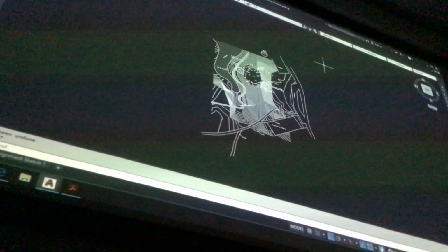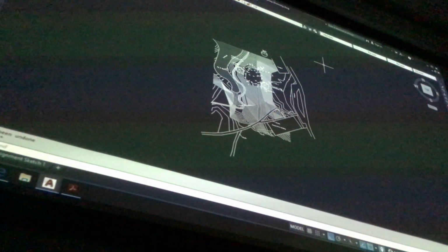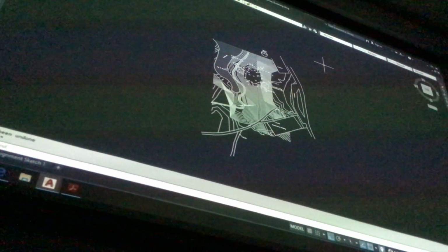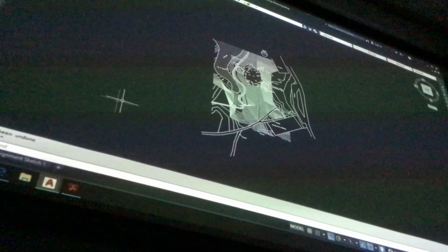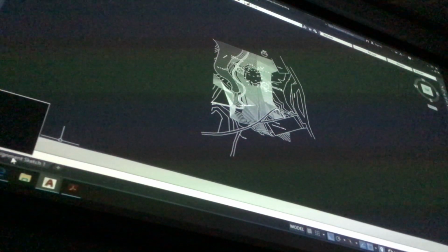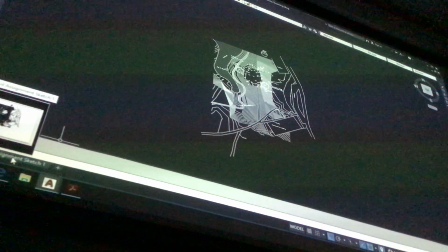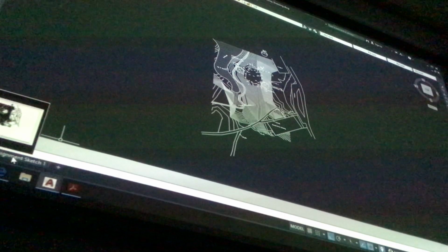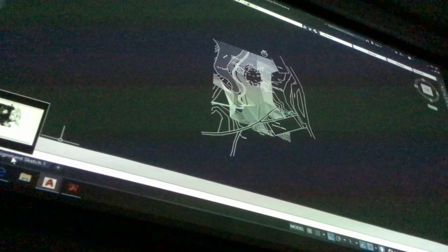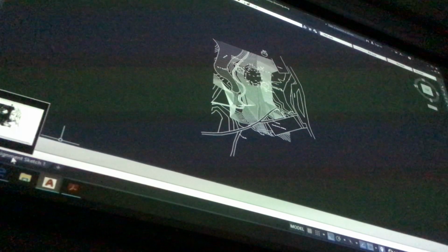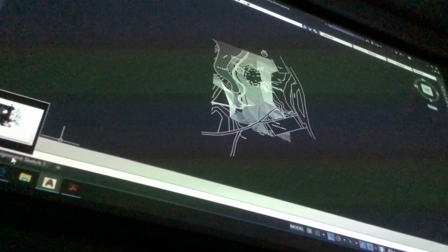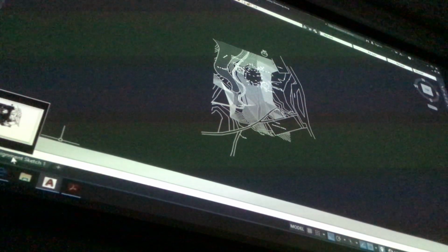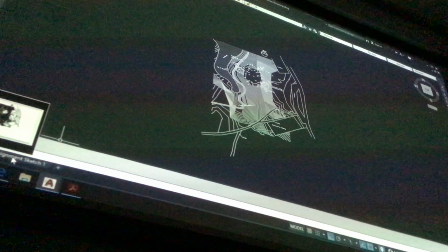Because you never know what might be sitting out further out that the surveyors or the company that's surveying decided they wanted to freeze and it really shouldn't have been frozen. Okay, the next thing I do is I'll go into my layout space. Now look at this. You guys have been given a layout tab that is already named. Isn't that brilliant? The only problem is it's got the wrong name on it. So you're going to have to come up with a name for the tab. In other words, what is this assignment called? What is this drawing called? So you need to right click on and change that.